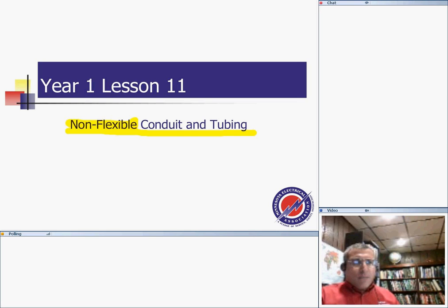I hope it will be interesting. We'll talk about construction of conduits and tubing, guys: rigid conduit, intermediate, ENT, EMT, PVC, and different characteristics of these conduits. Where you can use them, where you can't use them, how to support them, and so forth.